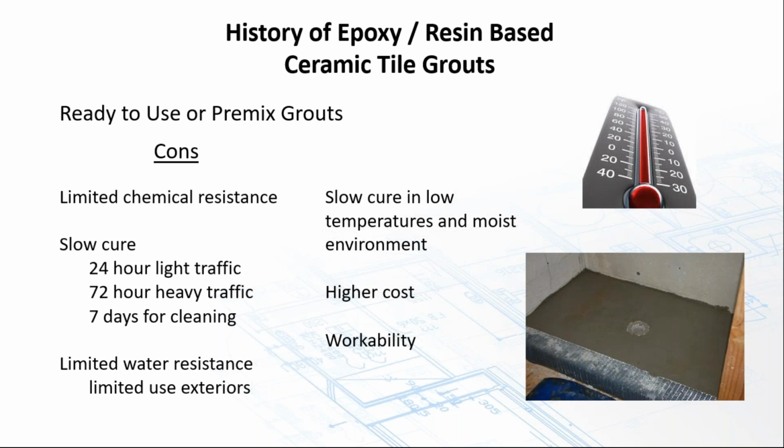Look at what these ready-to-use grouts can be used for. Heavy commercial or heavy sanding, soiling, heavy chemical use. It's not like an epoxy. They will break down under those types of conditions. So make sure that you're specifying this grout in the area where you expect it to be used, and not in a heavy commercial application.